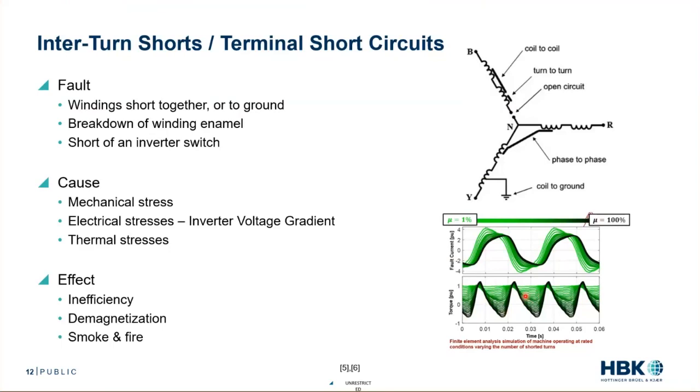So you're now experts on inner turn shorts. Basically, in that stator, windings get shorted together. They create big currents where we don't want them. They create heat where we don't want it. Not that we ever really want heat.